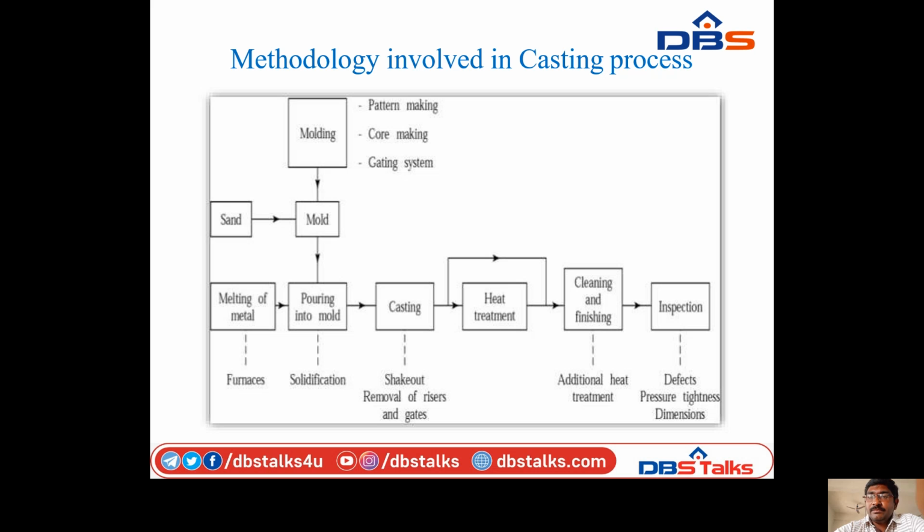So casting, then go to casting shake out, removal of risers and gates. Next, then go to heat treatment. Then heat treatment completed and going to cleaning and finishing or additional heat treatment. Next, inspection. So we can inspect the defects, pressure tightness, dimensions, etc.